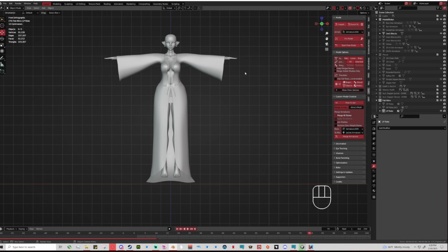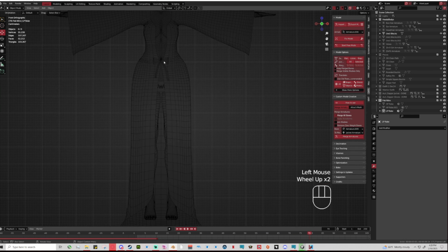Doing the average scale basically means that on our bow here, the quads are a lot smaller than they are here, right? But if we average them, then that's basically telling Blender and the UV map, which is going to be so important for our texturing, hey, I know that these are different, but whenever I put a texture on it, I want you to treat it as if it's the same. I still sometimes struggle to get it exactly right, but that is probably because of my UV mapping and where I put the lines.